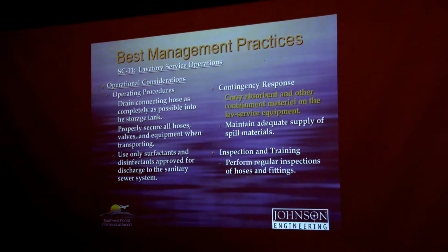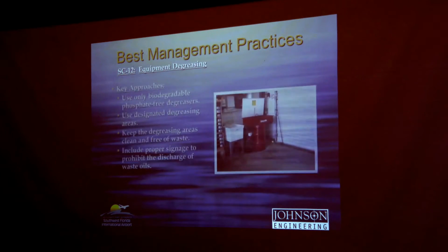Additional operational considerations include drain the connecting hoses as completely as possible into the storage tank, properly secure all the hoses, valves, and equipment when you're moving them, use only surfactants and disinfectants approved for discharge into the sanitary sewer system, maintain your adequate supply of spill materials, and perform regular inspections of hoses and fittings to make sure we don't spill that stuff on the ground.